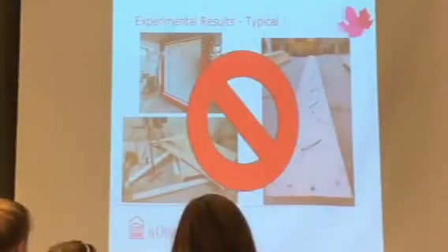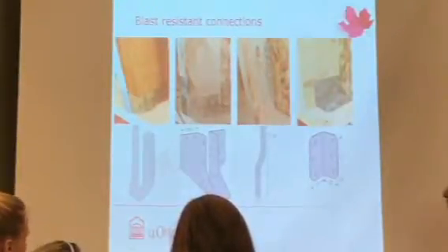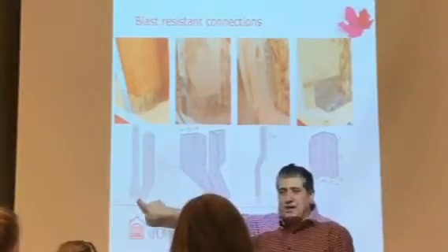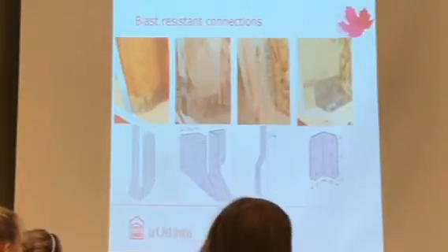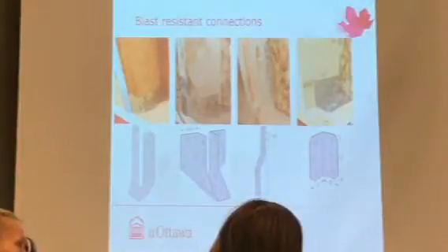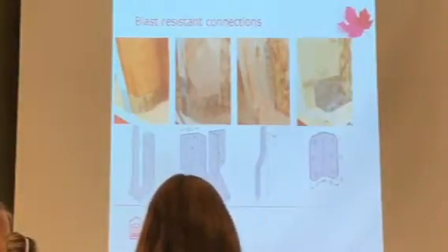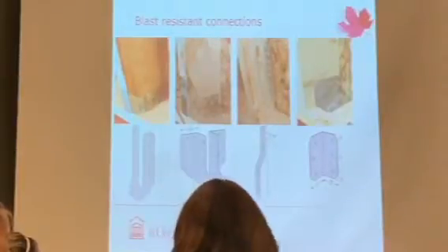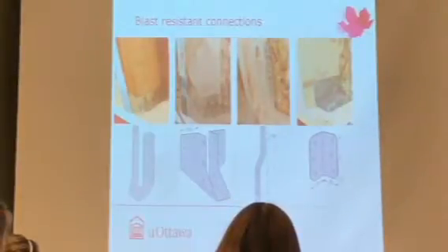So we said, okay, what's next? Let's look at different options. We looked at a joist hanger, a kind of flimsy joist hanger. These are hangers you use at the end of a joist like this. So assume that you have a concrete wall or something like that. And then you have a floor in the basement that comes in, a floor joist. What you do is you have maybe a top-mounted steel piece that goes like this and like that. And it's just attached to it. So it's just a saddle for your joist. So great. Let me take that saddle and put it at the end of the stud instead. So that way I have a support at the end of the stud.